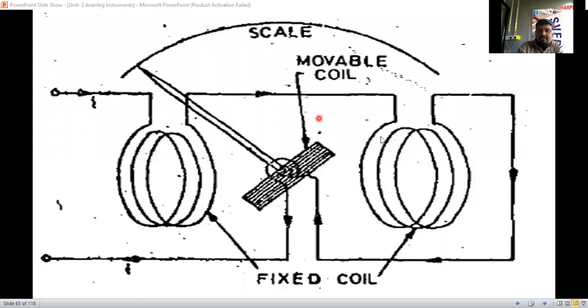You can tell that this circuit does not end here. The same current will flow through the moving coil also, through the brushes we have connected in the construction. So the same current is applied to the moving coil also. In between the electromagnetic field, a current carrying coil or conductor is placed, so it will produce a torque. A mechanical force will be produced here.